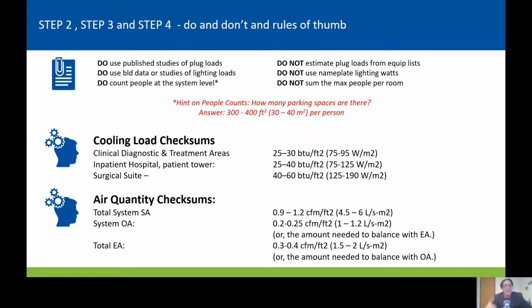The real data is actually lower than what you'll come up with just by doing a diversity factor. And then, of course, occupant loads are the last area of that. Occupant loads are a pretty significant source of error in load calculations. Obviously, our rooms need to accommodate the peak number of occupants in that room.